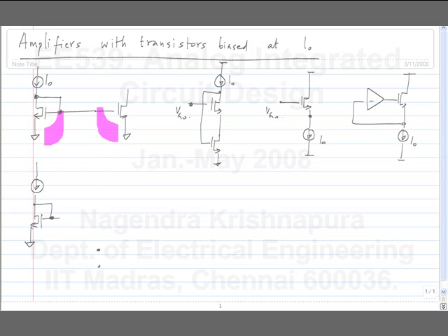If we have an input signal Vi here, how do we make sure that this bias appears across our transistor for DC and this signal appears across the transistor for AC? This is the DC bias. This is the AC incremental signal. We want essentially the sum of the two to appear at the gate of this transistor.